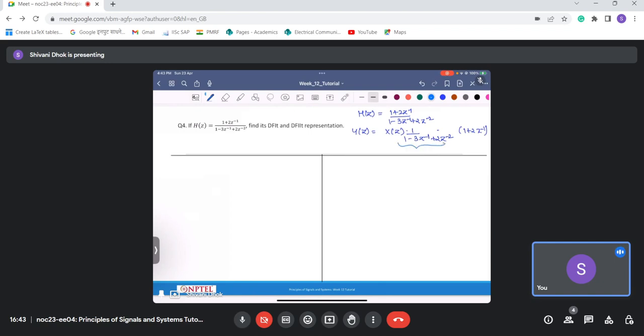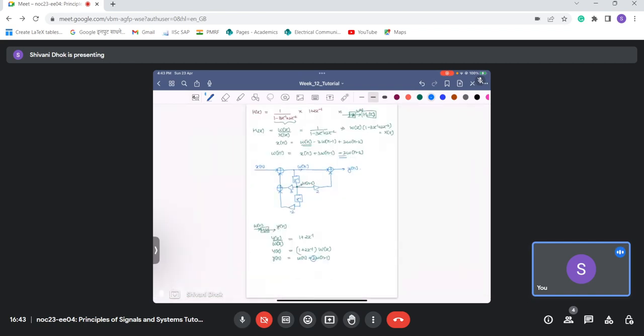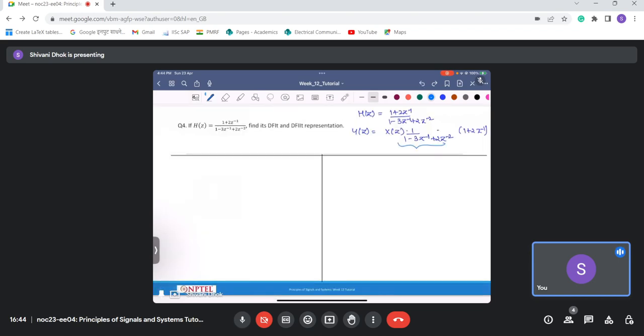Again, it is the same thing that we are realizing, but now we'll interchange the position of this delay block from here to here, and if we do that, we get the direct form 1 transpose. I'm just changing the position of this delay block and nothing else. These are just different ways of realizing any system. Sometimes one representation is better, sometimes another. It's simply a standard format to realize a system.